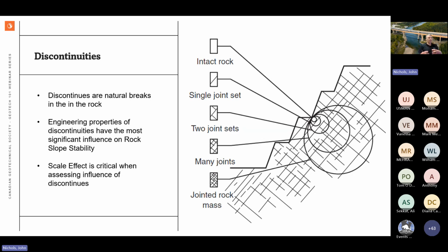Like the creation of these discontinuities, stresses are created in the earth by many different methods: plate tectonics, mountain building events, burial, sedimentation, glacial rebound, whatever. And these features help contribute to these breaks in the rock mass. The development of fractures is gradual at each stage, and in propagation the rock mass often loses strength before they can be fully developed. Therefore, rock masses will contain a network of planes of weakness at varying degrees of weakness. So not all these are created equal.